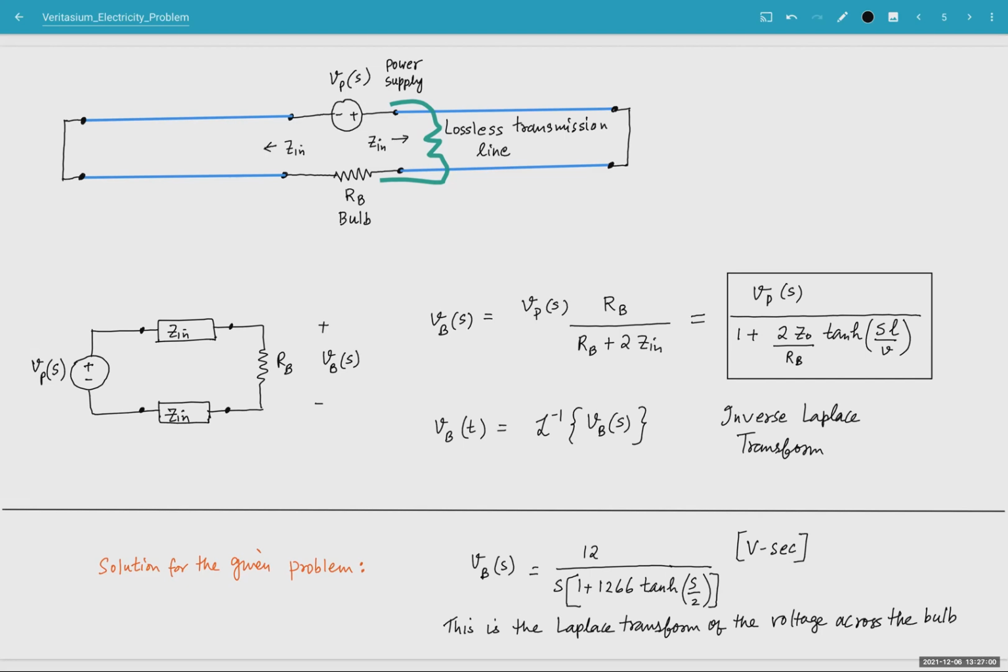And again, this value here is fairly large. This is Z0, which is 911.5 ohms for the chosen parameters. This value is fairly large because the shunt capacitance is fairly small, as the conductors are quite far apart in air, and this actually models the circuit very well.